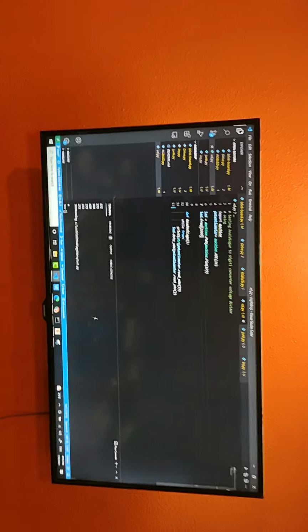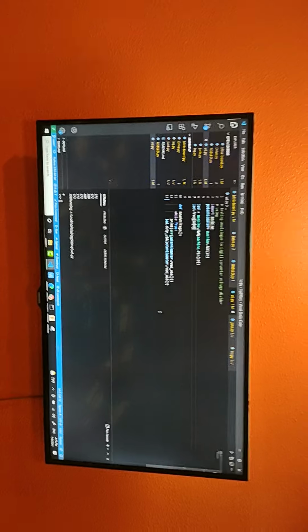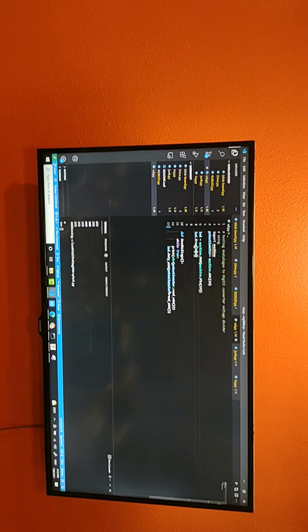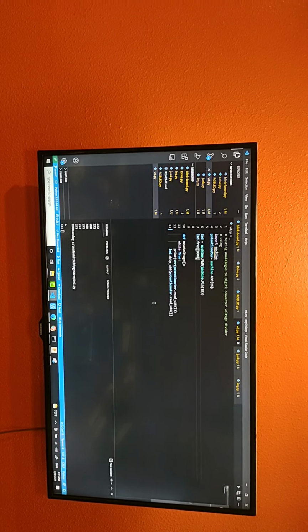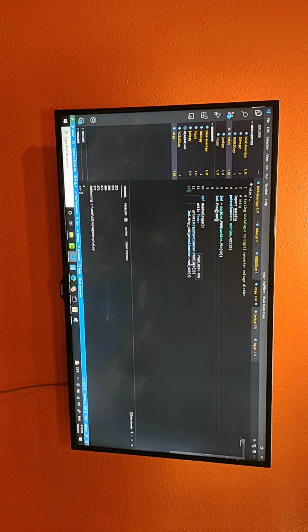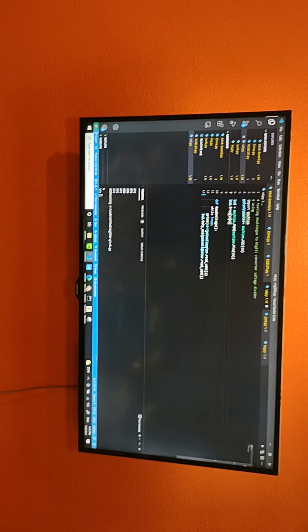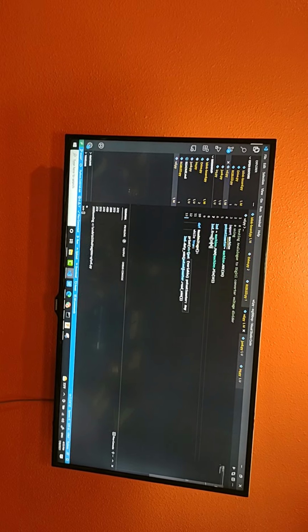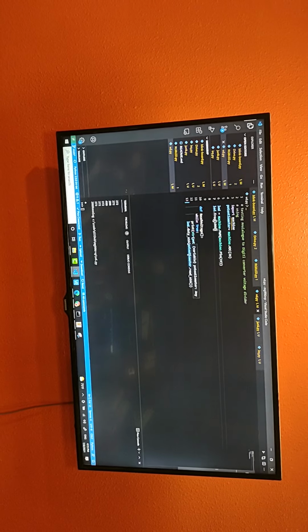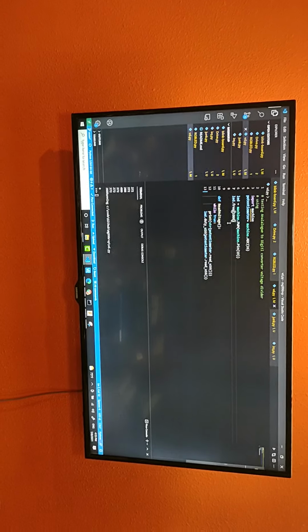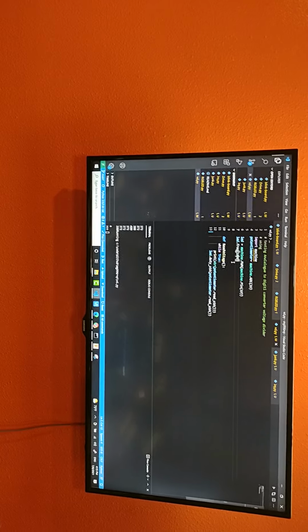And then the read voltage is a routine that runs while true, which is always, so it's going to print out the number that we saw at the bottom, and then it's going to feed LED.duty. The number we saw when we printed out was between 0 and 65,000. This method apparently knows that range, and it's taking a percentage of that. It's helping it figure out what percent of time it's going to be high versus low. Okay.